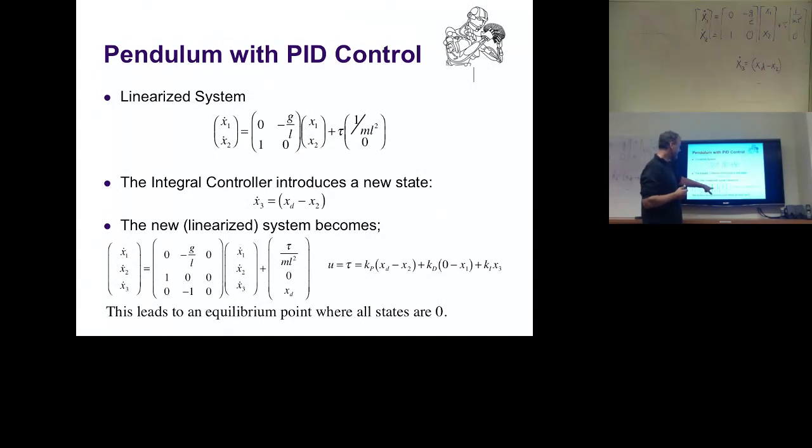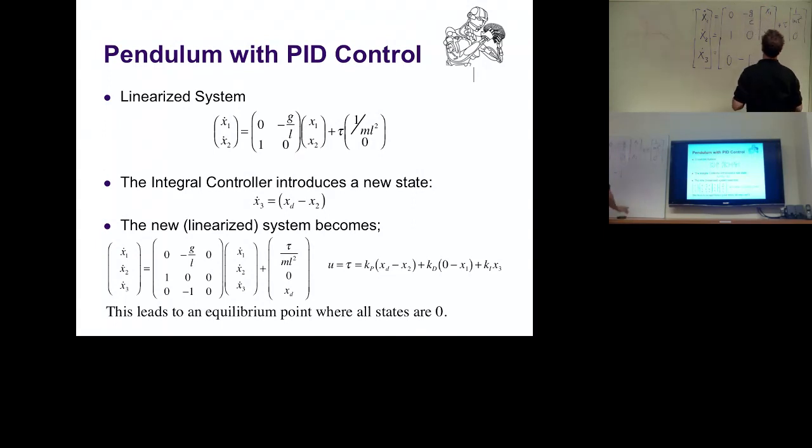And now we can essentially insert x3 in our system of equations. So we need a new state variable. That's very important. We create some kind of hidden novel state which does not really exist. It's a control state which we need. So we basically create now here x dot 3. Now I can finish my matrices. Here I'm going to get basically 0, minus 1. And I have to squish in a vector of zeros. So boring, but you see it nicely on the slide. And we get a state x3 here. And this here becomes also a 0. Okay?